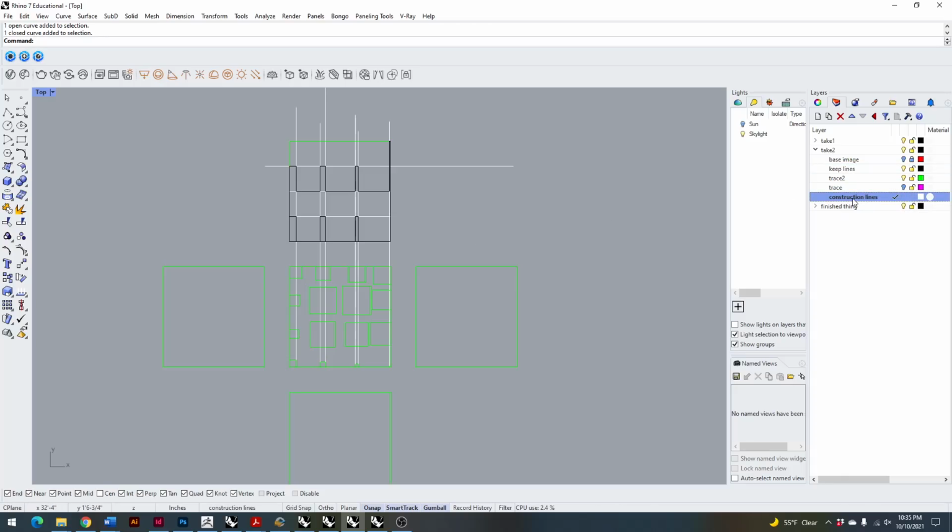So how we'll do that is we'll switch to the construction lines layer and we'll draw a line in space. We'll select that, and then clicking the arc, this blue arc here in your gumball, if you click it once, you'll notice this dotted circle with these arrows and a white bar that you can type into. These arrows indicate what would be the positive direction, so counterclockwise is positive.